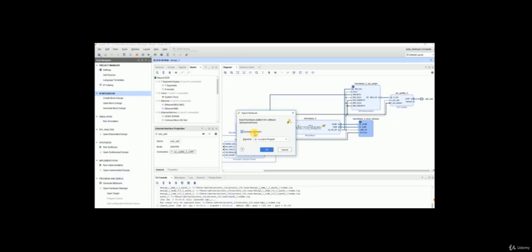One way is to program the FPGA from Vivado itself, and the second way is programming the FPGA from the SDK. We'll prefer the second way unless we will be debugging the communication interface or intermediate wires. Once you have a scenario where you need to debug the values of a net using an ILA probe, in that scenario we prefer to program our FPGA from Vivado itself. When you are least interested in debugging your hardware design, we like to program our FPGA from an SDK.